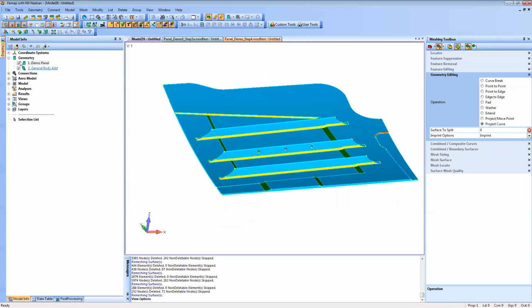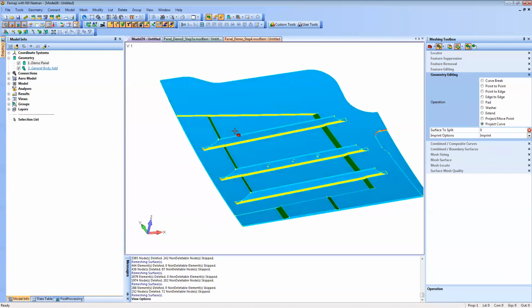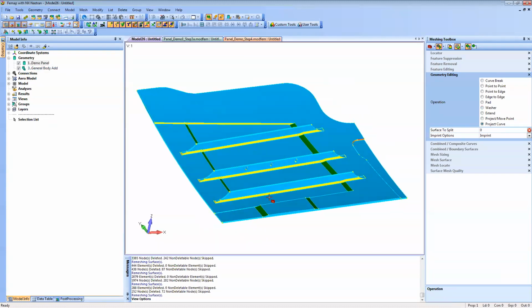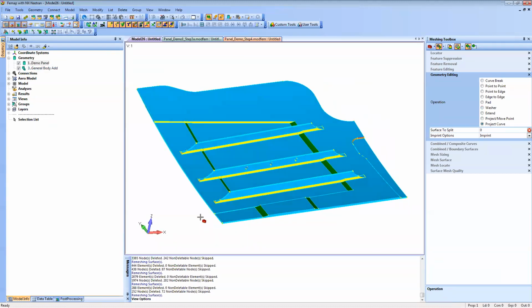I think what you did was probably the best. Andrew, I'm not sure if your question was asking about the tangent or if it was just the difference between the select or the select dialog box. So in the Meshing Toolbox, select that's highlighted right now, if you click that, that just lets you one at a time on the fly click things. If you do dialog select, then it pulls up the normal select menu. So then you can start selecting multiple curves at once, multiple surfaces and things like that.